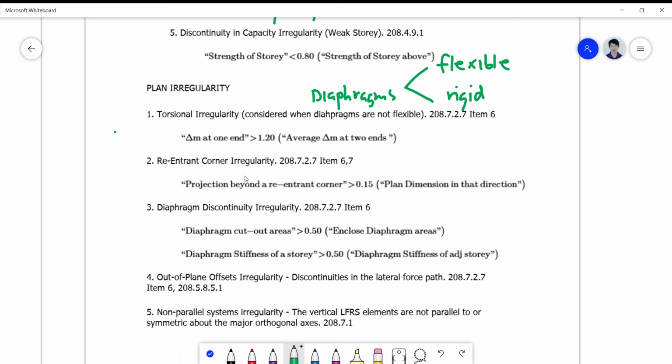Okay, so if you have basically two buildings here, and the earthquake is moving back and forth like this, the ends that you are referring to are these two ends here. Because this end and this end will just move the same if this is rigid, okay? You don't have to check it here and there because this will move just the same with this.